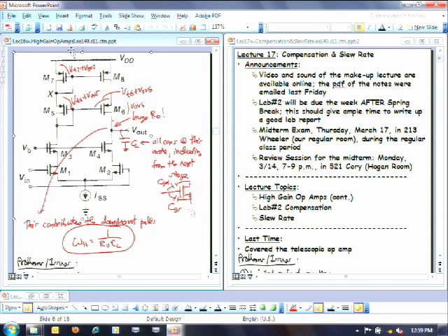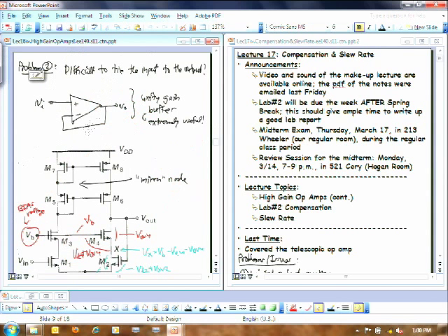and we found that the swing is not very good. Now, we went even beyond this and said, well, in a practical circuit, you're actually going to take an op-amp like this and hook it up in feedback. And maybe the simplest type of feedback you can think of is this unity gain buffer that you've all seen all the way back in EE40. Well, now you know what this unity gain buffer really looks like. It really looks like this circuit with all these transistors, except now you're tying the output to the minus terminal. And so that's what this line is doing here.